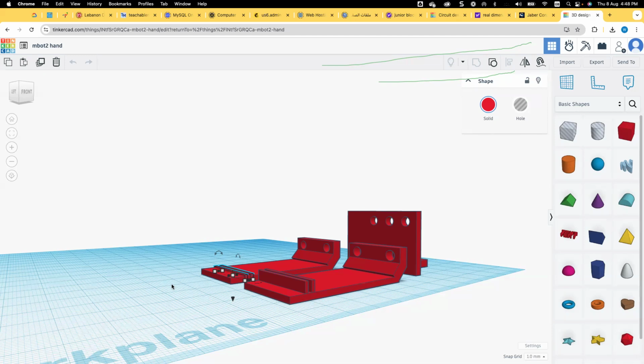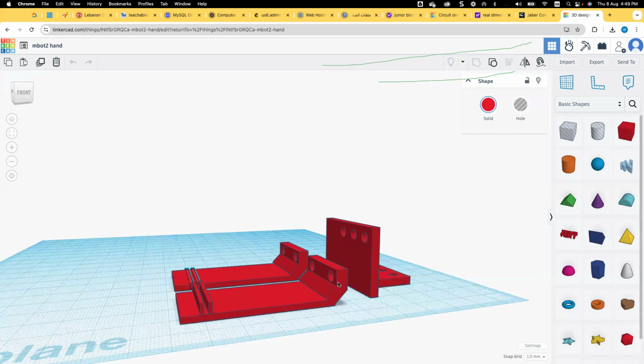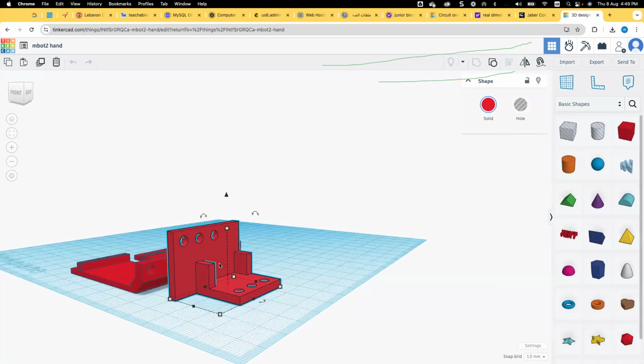And you can see that I've stuck on, with glue, something like a sponge, so that when I close my hand, it will fit in a correct way, and it will not move the other cubes that are next to the cube that I'm catching. And finally, the base that I've created here is black. This structure is to fix on the skeleton of the robot, and at the same time to hold the two structures that I have as hands for the servo motor.